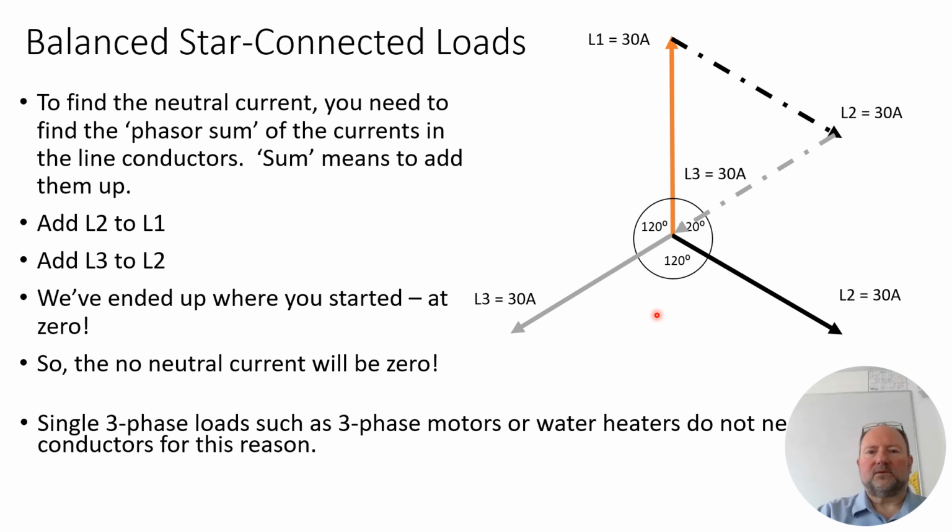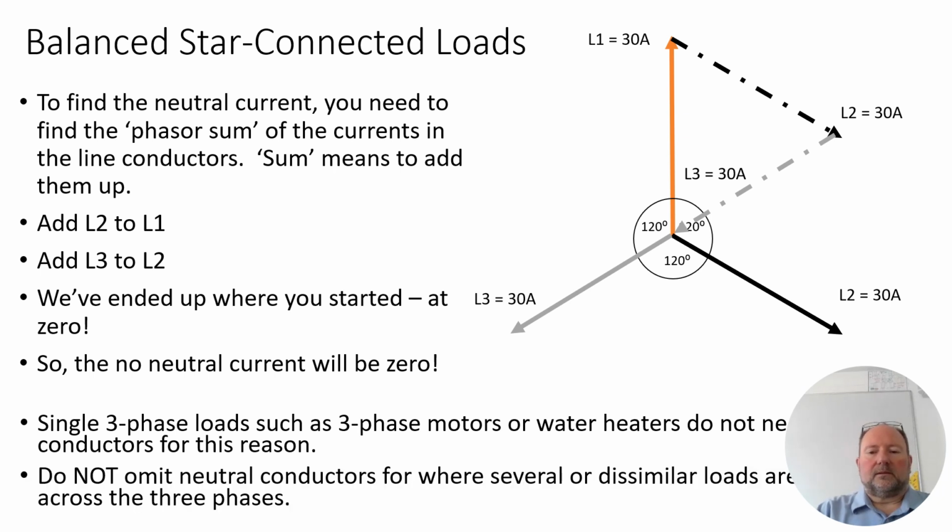And like I said, for single items of three-phase equipment like motors or heaters, they may not require a neutral conductor. If it's a motor, it's very uncommon to see a neutral conductor on a motor. Please do not do that though if you have an unbalanced load. Please do not omit the neutral conductor. You definitely need the neutral in there if you're trying to do lots of single phase loads, right? Don't omit the neutral.